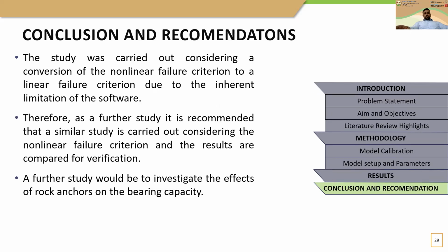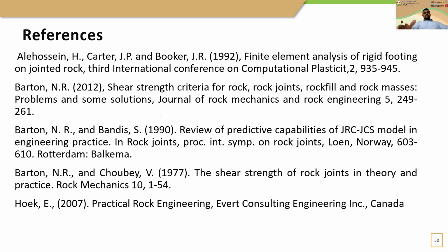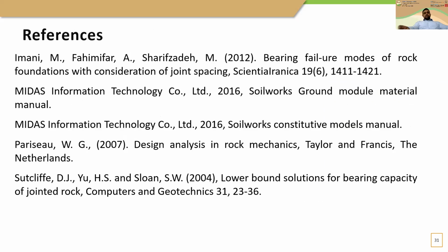So further recommendations for this study: the study was carried out by converting the nonlinear failure criteria to linear failure criteria due to the inherent limitation of the software, as I mentioned before. Therefore, it is recommended to carry out a similar study considering the nonlinear failure criteria, if it becomes available in the software later, and verify if the same results can be formulated. A further study would be to investigate the effects of the rock anchor on the bearing capacity. So these are the references that I have used for the study.